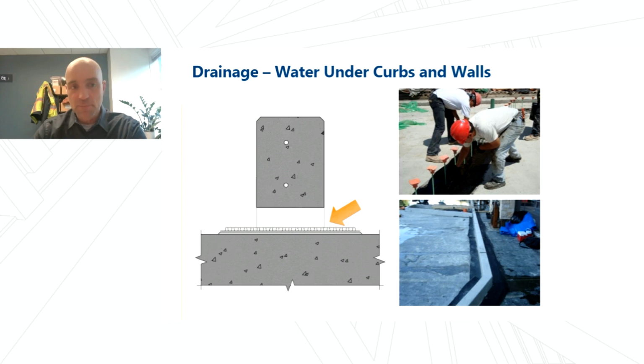My personal opinion, it's low risk to drain water from the plaza into the planter. I'd rather we didn't drain water from the planter out into the plaza. I think doing so risks bringing soil and other debris with the water that could wind up obstructing the drainage course in the plaza.